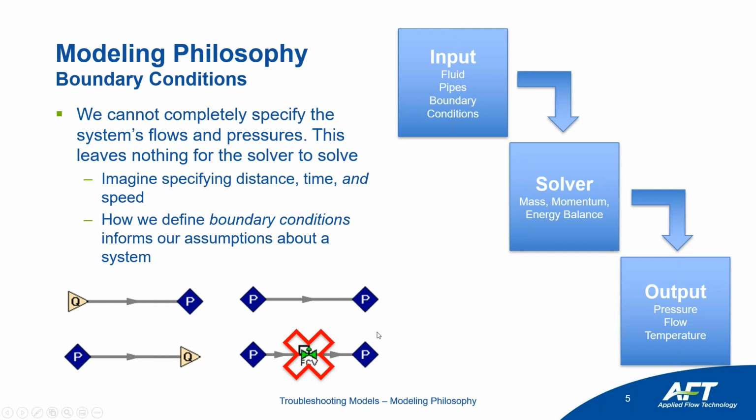So it's very important to understand these boundary conditions because again, garbage in is garbage out. You're going to hear that a lot throughout this webinar. And so by defining your system, you're inherently making assumptions at the edges and at the boundaries: is this fixed as a pressure or is this fixed as a flow rate? And when I make any other change to the system, whether that's swapping out the pump that I have, or valves, or opening or closing different lines off, will those boundary conditions be maintained? And we want to make sure that we're not trying to create boundary conditions just to meet field data.